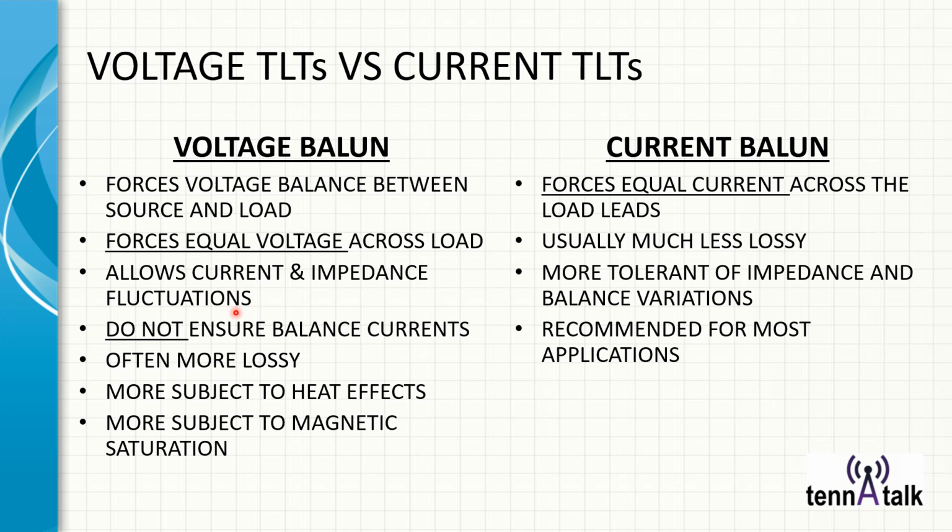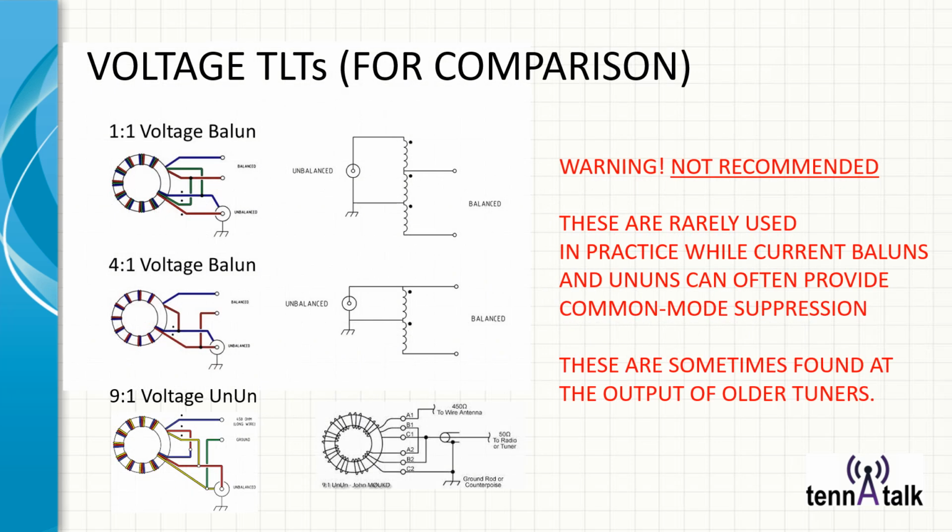Voltage baluns, however, are really not favored. They were built into older devices to accommodate tube outputs and other high-powered tuners of older days, but they have some subtle issues that can creep in and would be hard to diagnose. So just take a look at that. You can see there's just a few differences, but I want to point out that these are voltage baluns if you happen to see them, okay? And they are not recommended.